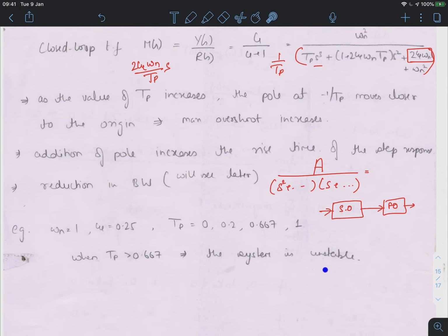All the poles of the forward path, except one located at the origin, are stable, but once you do the analysis in the closed loop system, the closed loop transfer function becomes unstable. Verify this by yourself. You can use MATLAB to plot the responses.